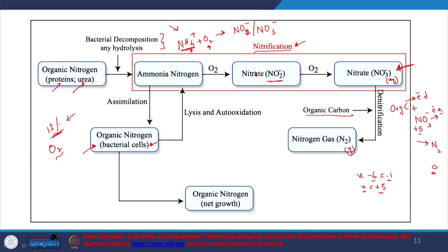One thing to note is that in the usual activated sludge process, where we are degrading the organic content or our waste, oxygen is also the electron acceptor. That is good enough for nitrification. But for denitrification, NO3 minus is the electron acceptor. So if oxygen is present in the system, denitrification will obviously not take place.